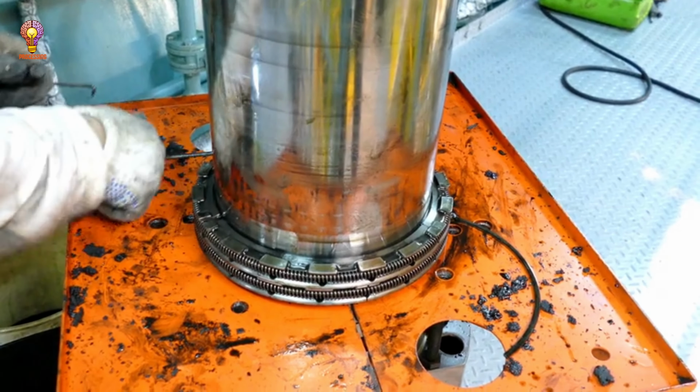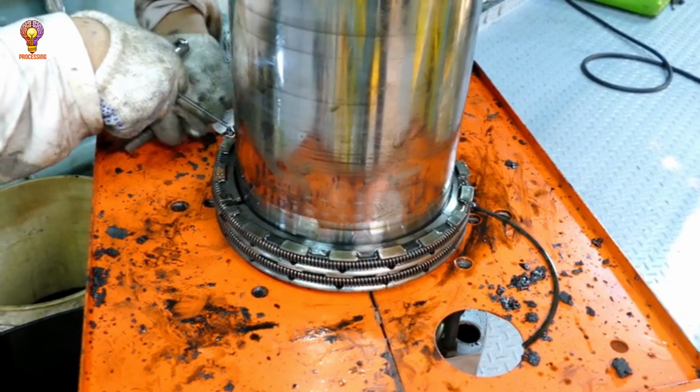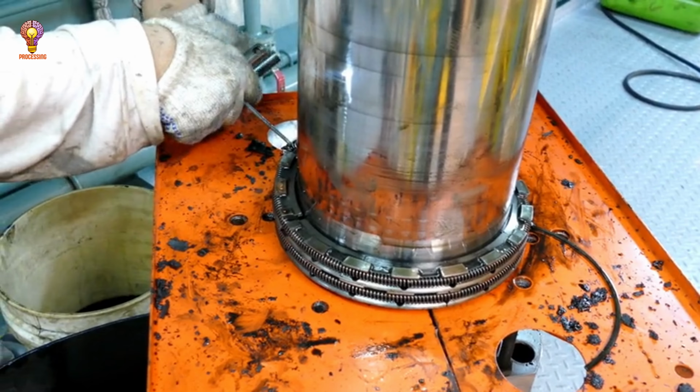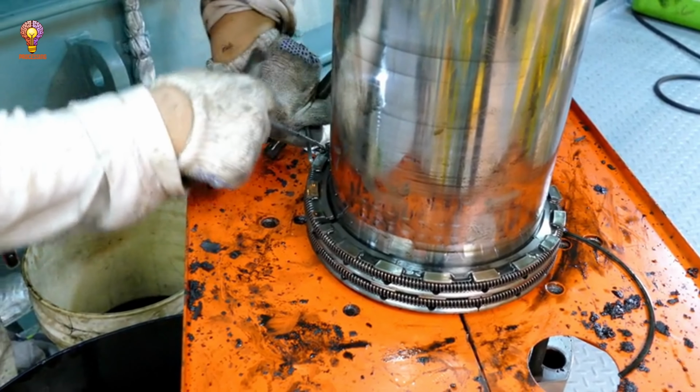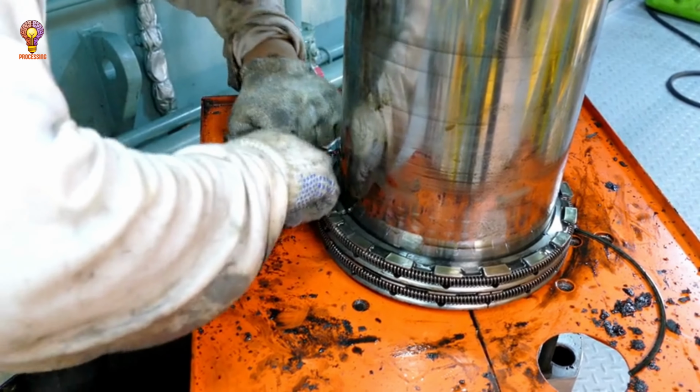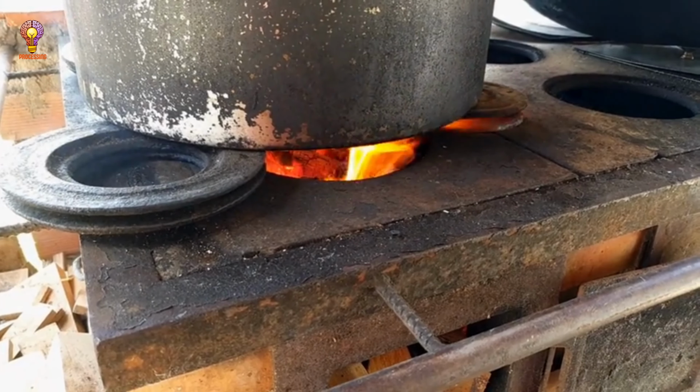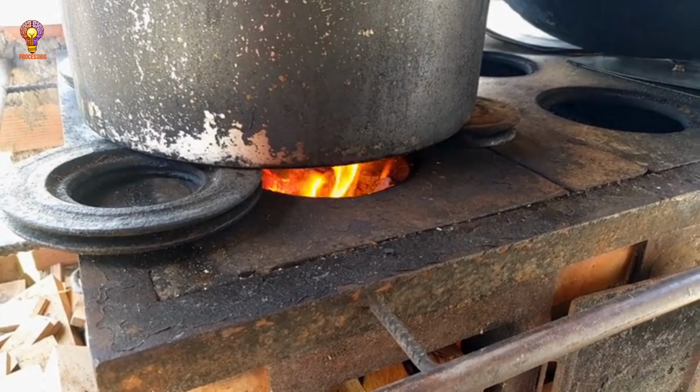7. Finishing processes. Some of the common finishing processes include pickling, a process to remove oxide scale and rust from steel surfaces using an acid bath, typically hydrochloric acid. Galvanizing. Steel is coated with zinc to protect it from corrosion. This is done by dipping steel into molten zinc or through electrogalvanization.